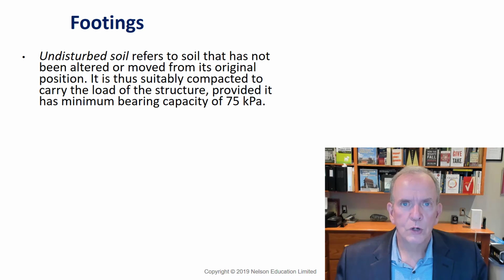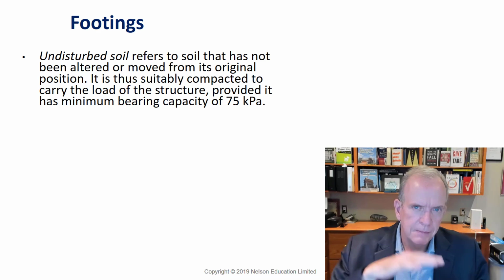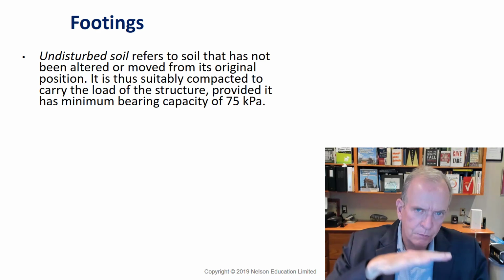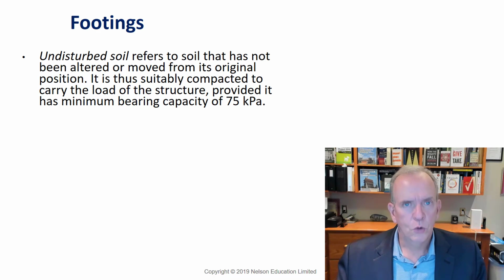It may be the soil capacity. The bearing capacity of the soil is not strong enough to support this structure. For example, if you're building on swampland, you've got a lot of peat, topsoil and decaying material, and it's spongy. You ever push your hands on topsoil? It's kind of spongy. That's not good for placing a foundation on. So the bearing capacity has to be suitable to carry that.